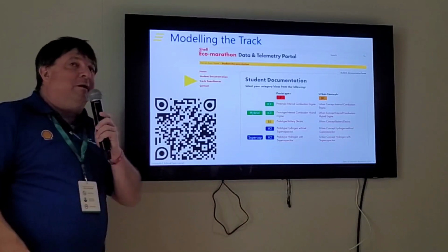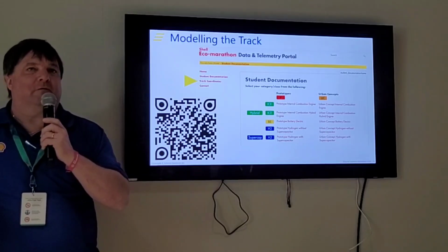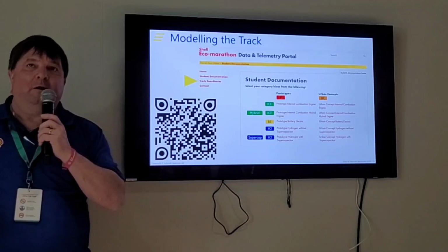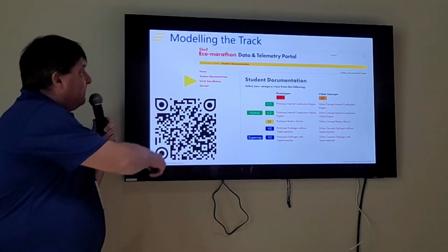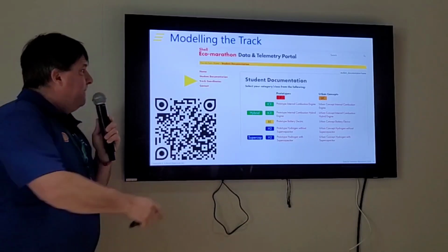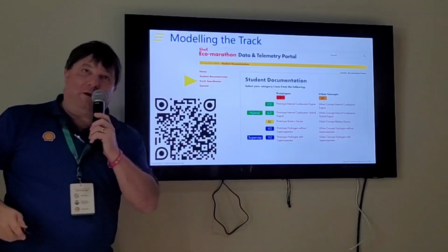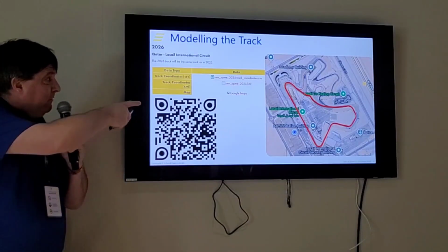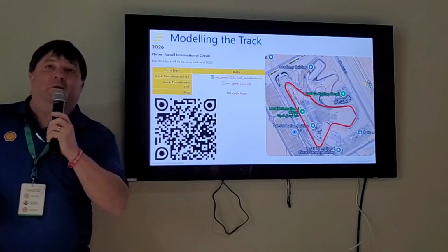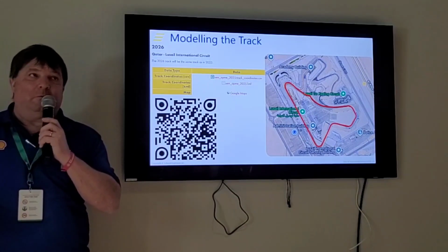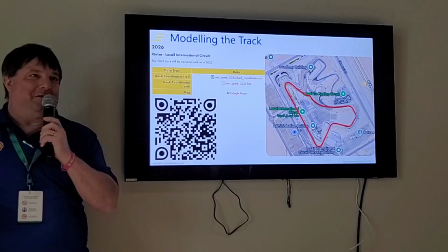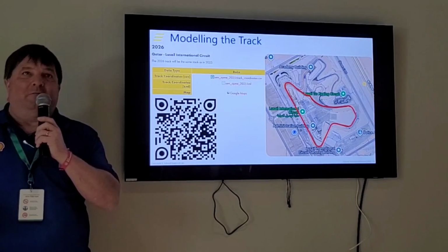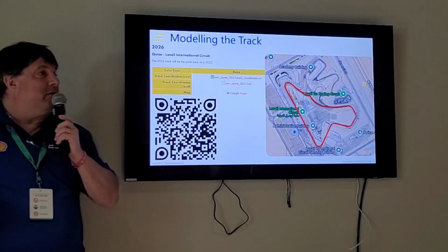So you can start with the track data. I've seen that in many off-track award submissions you use Google Maps to extract data from the racetrack, maybe without knowing that through this QR code you get to the telemetry wiki, and you receive the track coordinates actually from Shell. They give you the track coordinates like the Lusail track. That includes also the elevation. There's not much work other than downloading this CSV file and using it in your modeling environment. So, using the racetrack as a model.